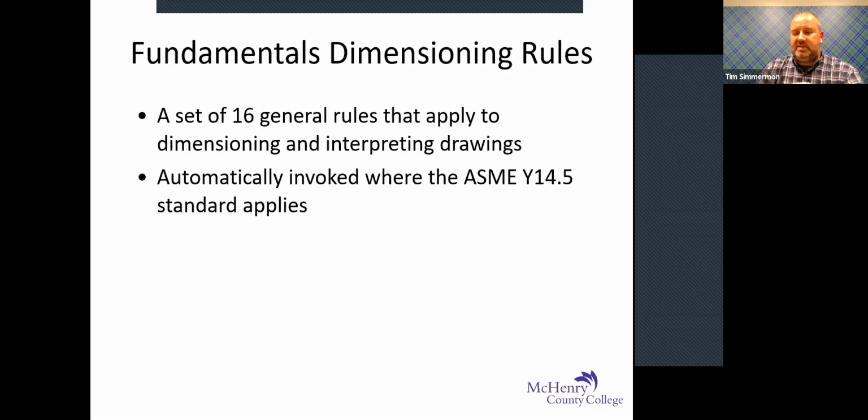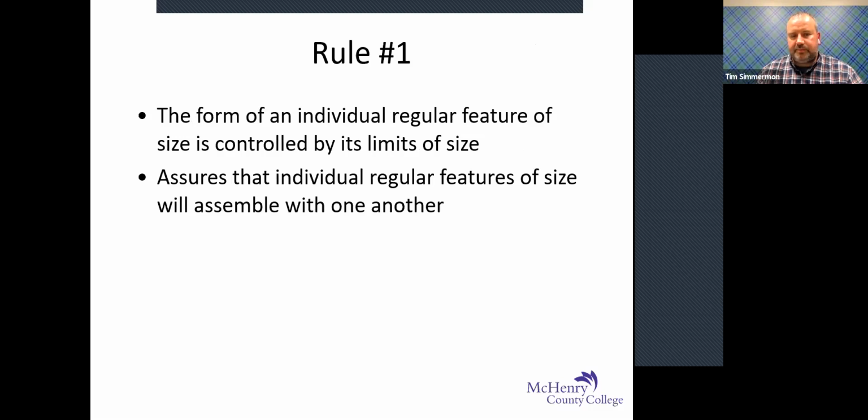It's really easy to make a blueprint that doesn't have all the dimensions on there or isn't toleranced correctly, but you know that it needs to fit pretty good, or you know that this needs to have a really shiny surface finish on it. But it's just tribal knowledge that's been gained over time. Once you dimension your blueprint accurately, then anybody can repeatedly make that part to the same tolerances and same standards that you would make that part to.